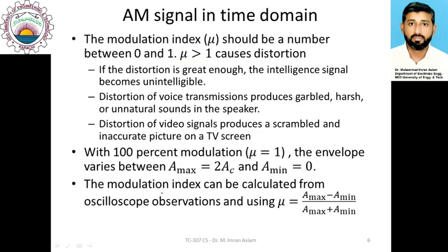One more thing I want to present is that we can calculate the modulation index by observing the AM waveform on the oscilloscope.